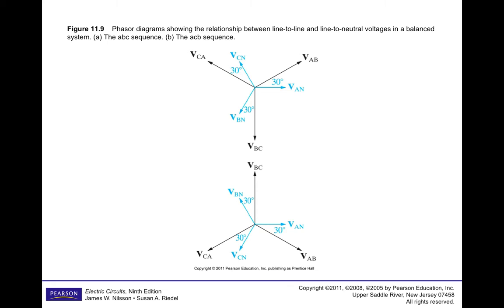And I think I mentioned before that when you talk about three-phase in a commercial application, you're almost always talking about the line-to-line voltages, and that's what electricians will tend to measure when they come out and work on your three-phase in your house or in your business. They're often more interested in the line-to-line voltages because that's what's typically running the load.